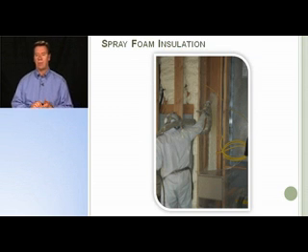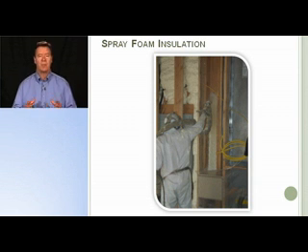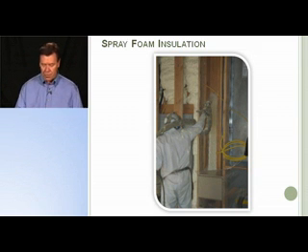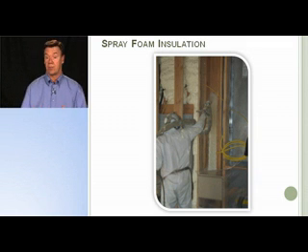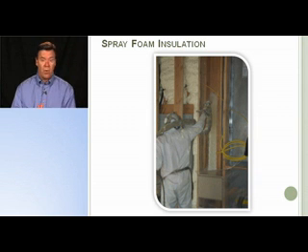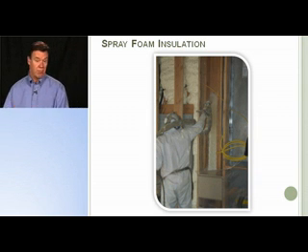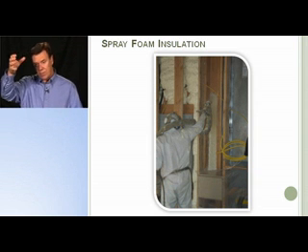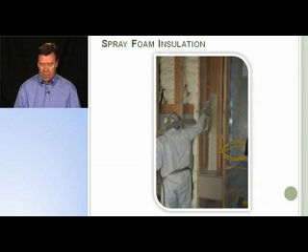There's other types of insulation that we use. For example, this is a person spraying spray foam. Spray foam insulation basically creates thousands, if not millions, of little bubbles per square foot that help trap air. So foam is probably one of the better insulators in terms of R value. We also have blown-in cellulose, for example. Oftentimes we'll retrofit walls that have no insulation and we'll drill holes in them and then take, much like a giant blower, a tube, and we'll actually blow insulation into that wall cavity to fill it up with basically cellulose, which is chopped up newspaper.